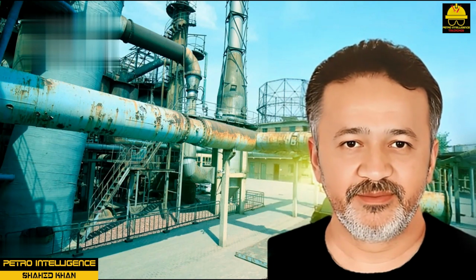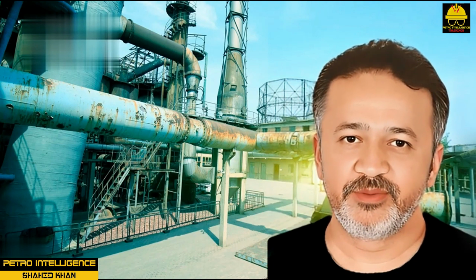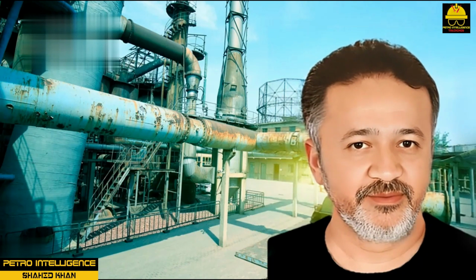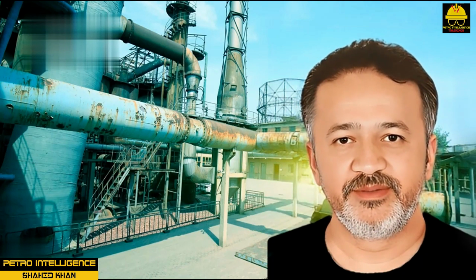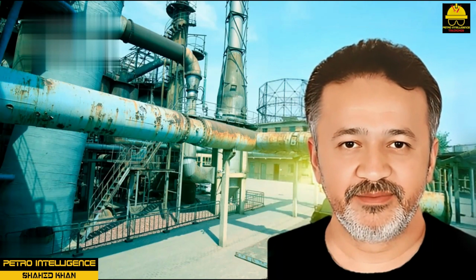Water treatment in boiler. Water treatment is classified as external or internal. External treatment takes place before raw water enters the boiler. Internal water treatment complements the external process and helps protect the internal components of the boiler system. In some systems, external treatment is limited. The primary location for water treatment is at the boiler. Common tests on boiler feed water include pH and the presence of particulate matter, measured in ppm, iron, oil, and silica.